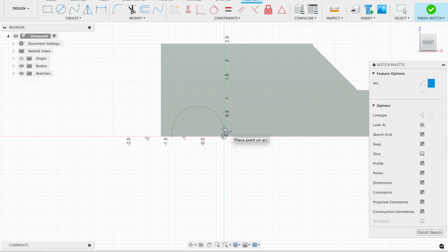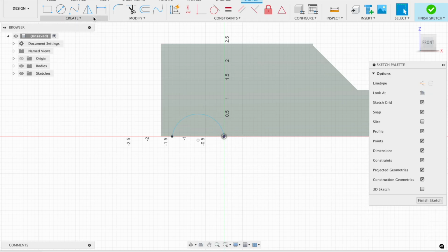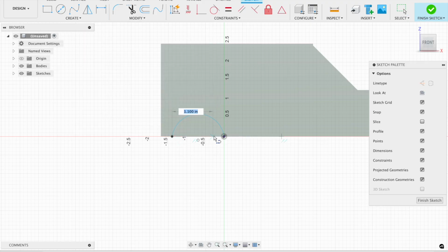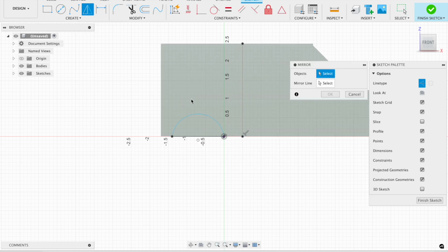You'll see me use it in this clip, and you're also going to see me set a construction line. A construction line just means that it isn't shown in the final thing, and you honestly just click it. It's really easy to use, and really helpful with functions like mirror that replicate the other side. I really like the mirror tool. It's very helpful when I need something fast and quick that is symmetrical.